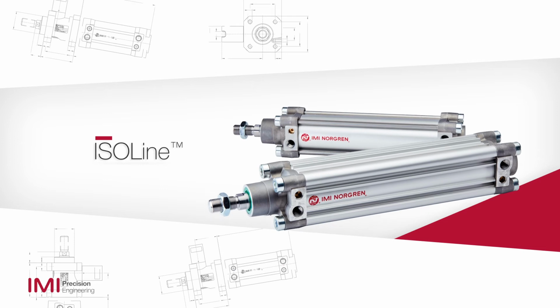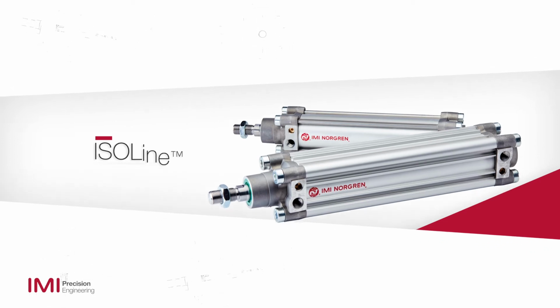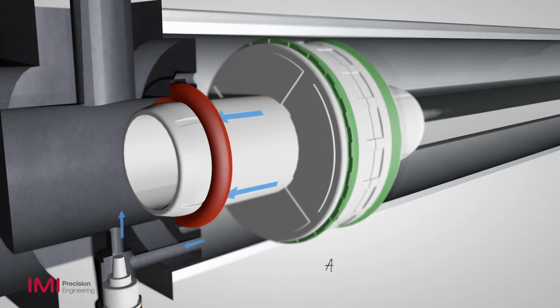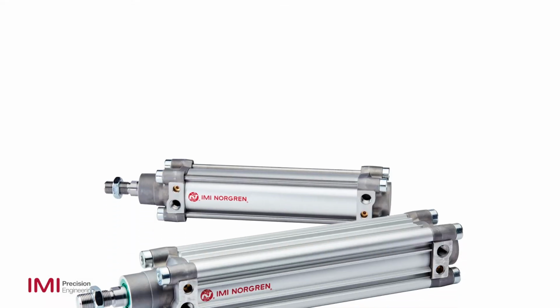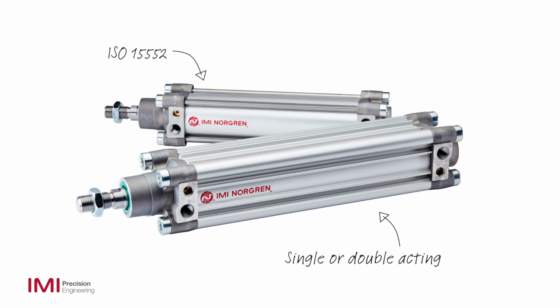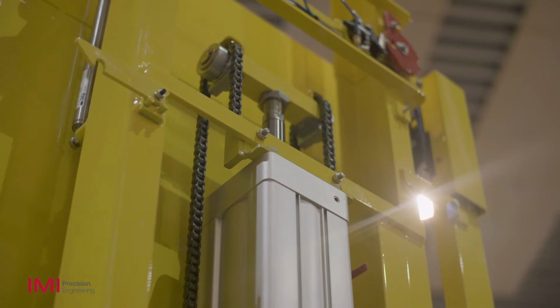The ISO line is a significant improvement over its predecessor. The cylinder is 15% lighter and with ACS cushioning technology. Available as single or double acting, it conforms to ISO 15552. It has flush-mounted switches to avoid damage, is fully configurable, and comes with a magnetic piston as standard.